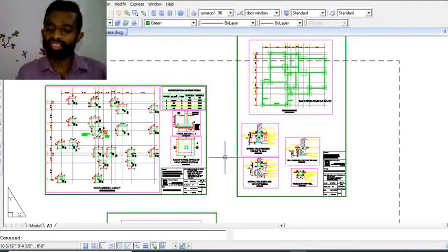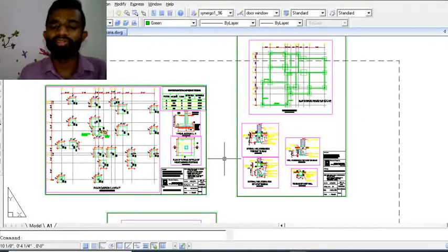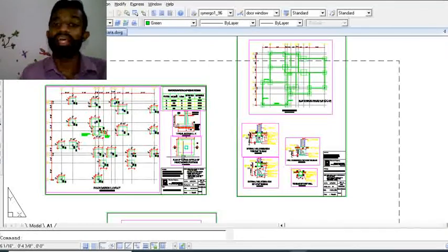And the other one is live load. For the live load, they consider people going onto the slab and using it; the weight coming from people or living beings is considered as live load. It's an assumed value. In the relevant codes of practice, those values are indicated, and using those codes of practice, structural engineers will apply these live loads and dead loads and analyze the structures.